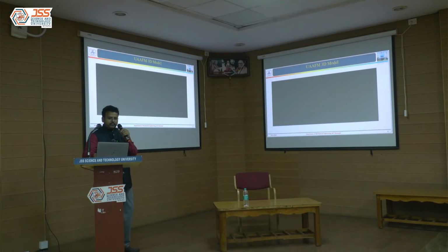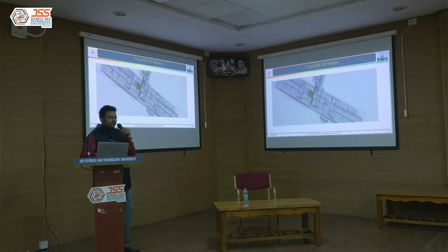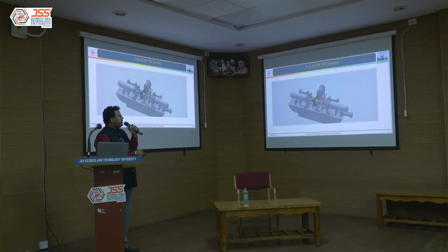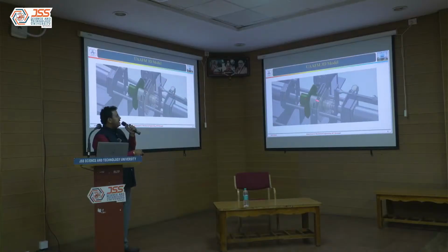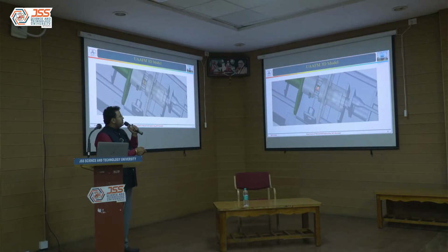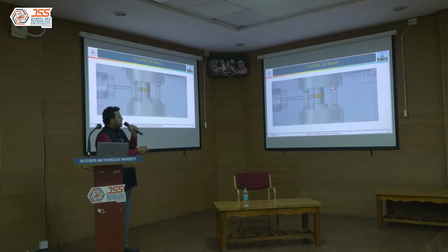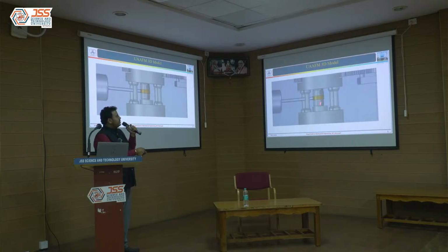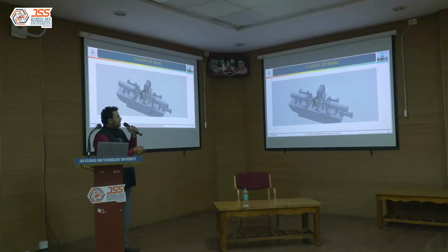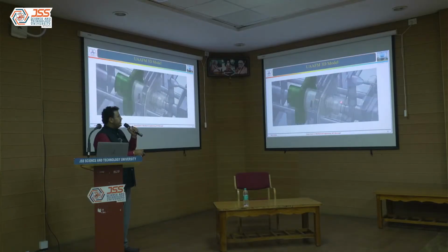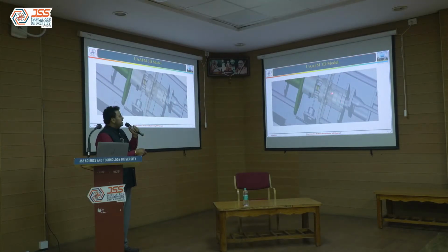There is a small video. When we developed the setup, initially we made a 3D setup. Here you can see the fixture and the workpiece vibrating at high frequency while pumping the media to and fro. This was developed in SolidWorks, and the same design was then fabricated for real-time machining.